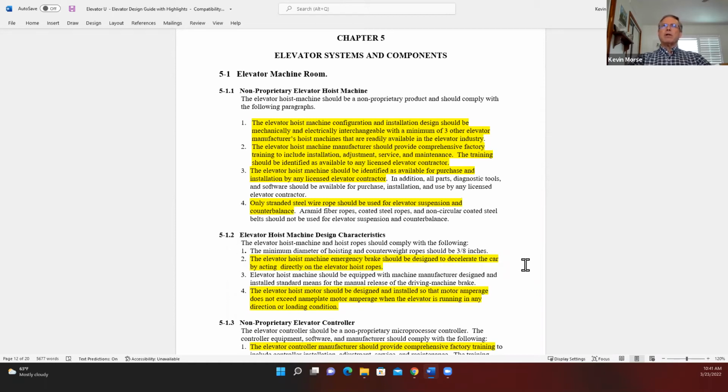The elevator safety code, when the paragraph was prepared for the requirement for an emergency brake, specifically and deliberately says that the suspension will not be considered in the design and operation of the emergency brake. So it allows for an emergency brake to stop the sheave and not protect against the hoist rope slipping traction and the elevator flying up the hoistway and slamming into the overhead, or flying down the hoistway, or if it is heavily loaded, hitting the buffers in the pit.